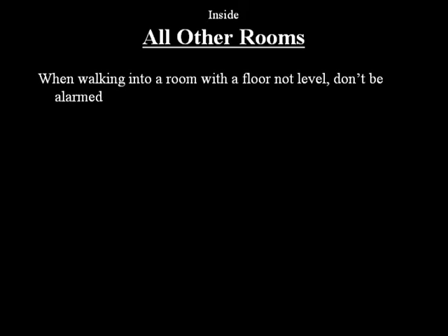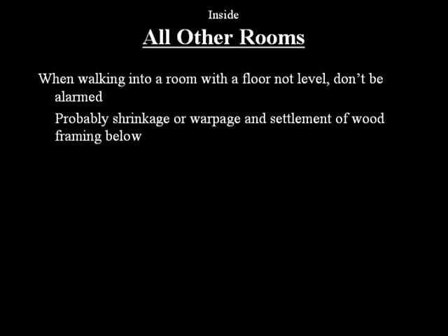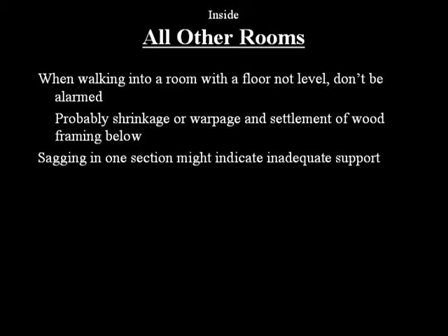When walking into a room with a floor that is not level, don't be alarmed. This is probably shrinkage or warpage in settlement of the wood framing below. Floors that have sagging in one section might indicate inadequate support.